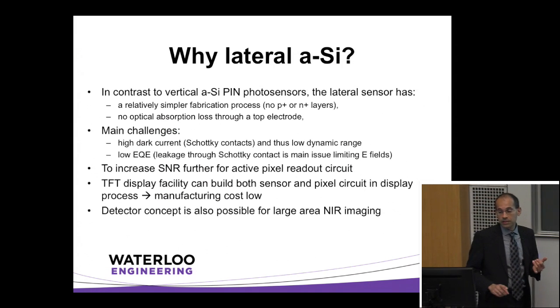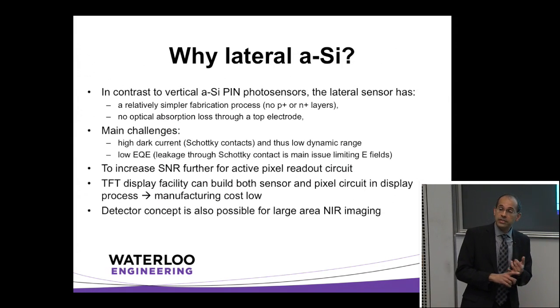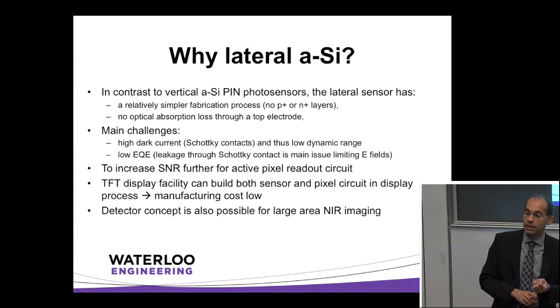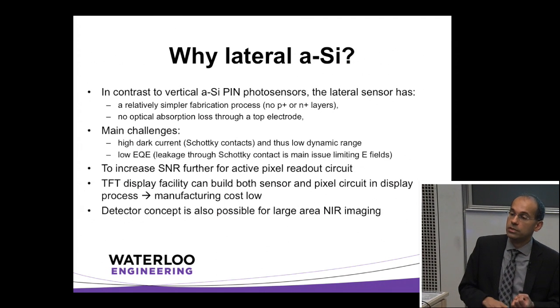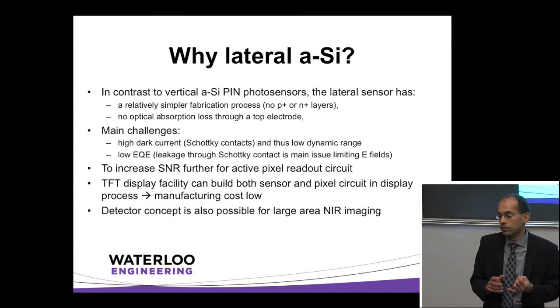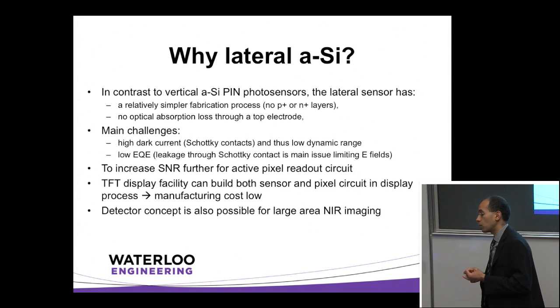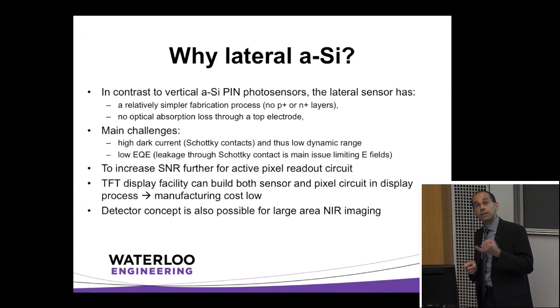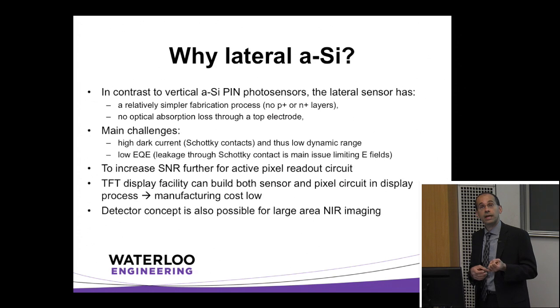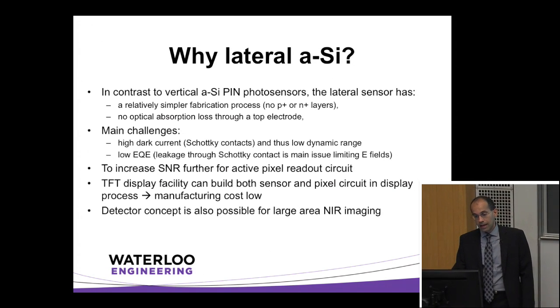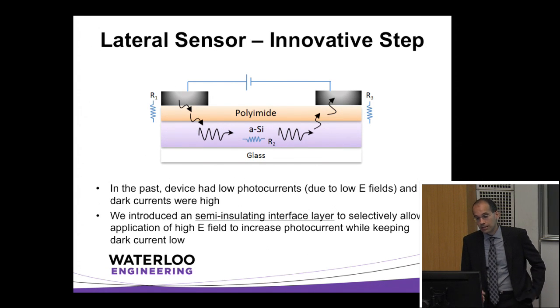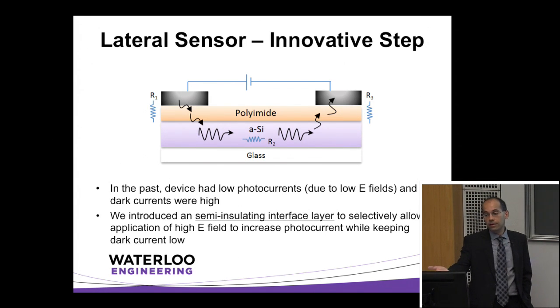But the neat thing about this technology is it's very simple. There's no p-doped layer, so it's not going to contaminate your TFT line. There's no ITO layer on the top, so it's not going to take away your fill factor or your quantum efficiency. It can be built in a standard TFT fab, so any LCD TFT facility in Asia. The biggest challenge is how do you get the device performance to match a PIN photodiode, okay? And the big challenge that we ran into here was, well, how do we get the performance to match?